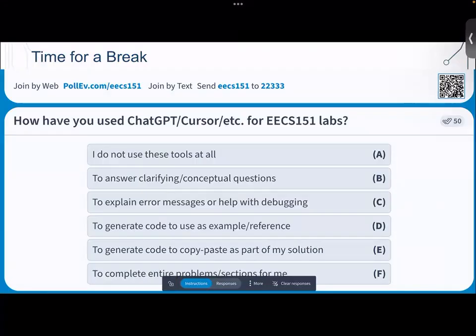We perform the logical effort analysis, right? We talked about how for specific gates, any gate topology, we're trying to figure out how much worse of a driver it is compared to the reference. The point of that is you want to have your N and your P networks balanced.